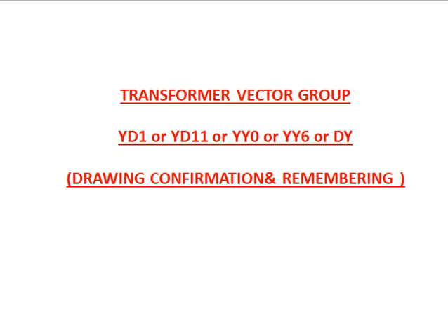with the grid. If you see the wall clock, 12, 1, 2, 3 are written on it. 12 means 12 o'clock, 1 means 1 o'clock, 2 means 2 o'clock like that. The angle between each is 30 degrees. 12 o'clock is considered as reference. If you say 2 o'clock, the angle between 12 and 2 is 60 degrees lagging. If you say 11 o'clock, the angle between 12 and 11 is 30 degrees leading.